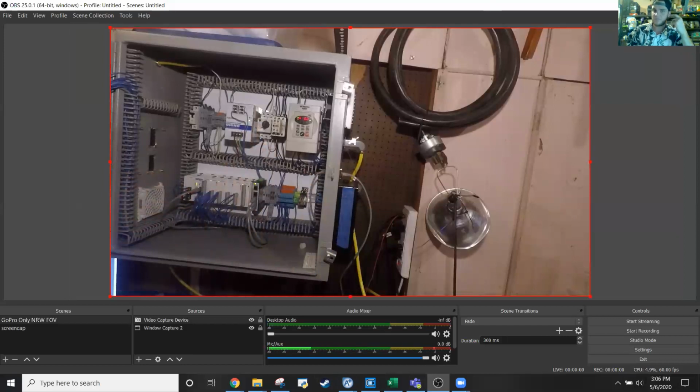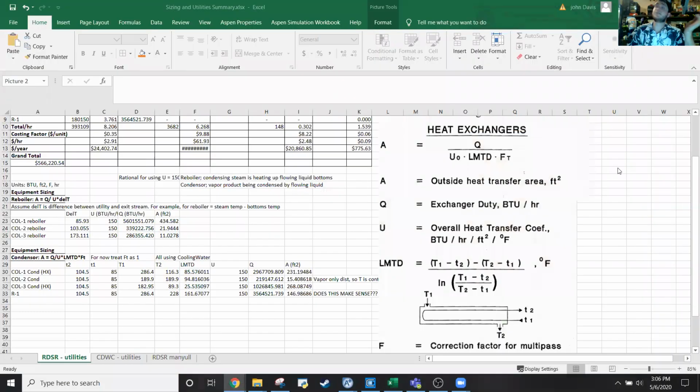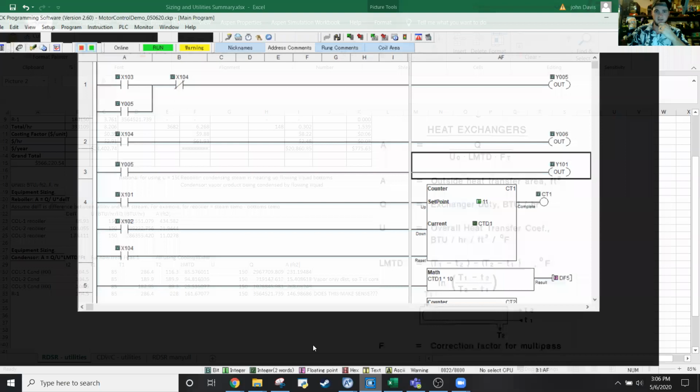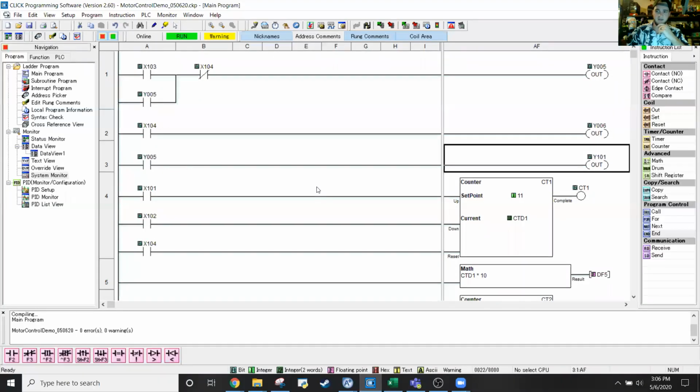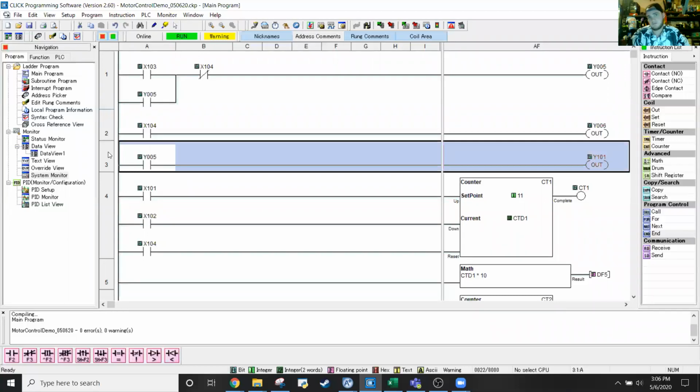And the reason, well, there are multiple reasons to have that. But a big part of it is that it helps physically protect your VFD internally. Your VFD will actually get burned up internally if you don't have that, from my understanding. I'm not an expert on this stuff, but it's important to have that. It also just lets you have another level of control, because as you can see here, if you don't have this rung in your code, physically that signal can't get to the motor.